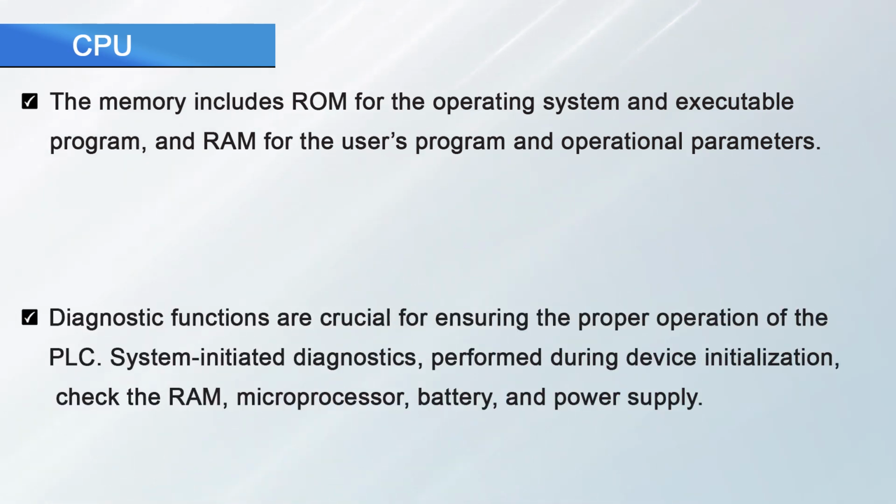The operating system is also responsible for the execution of various diagnostic functions from the Central Processing Unit. The diagnostic functions are crucial for ensuring the proper operation of the PLC. The system-initiated diagnostic is performed during the device initialization. It checks the RAM, the microprocessor, the battery and also the proper power supply.